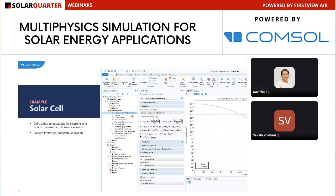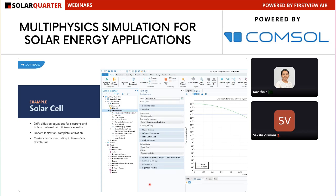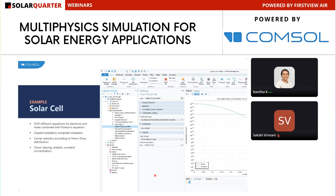So here in the semiconductor physics interface, in this example, we have considered complete ionization for the dopant. Here we are considering the Fermi-Dirac distribution to consider the concentration level, and we solve for the electron and hole pairs. In the physics toolbar, you can choose the analytic doping model for the domains, and we choose donor doping as N-type from the impurity list.